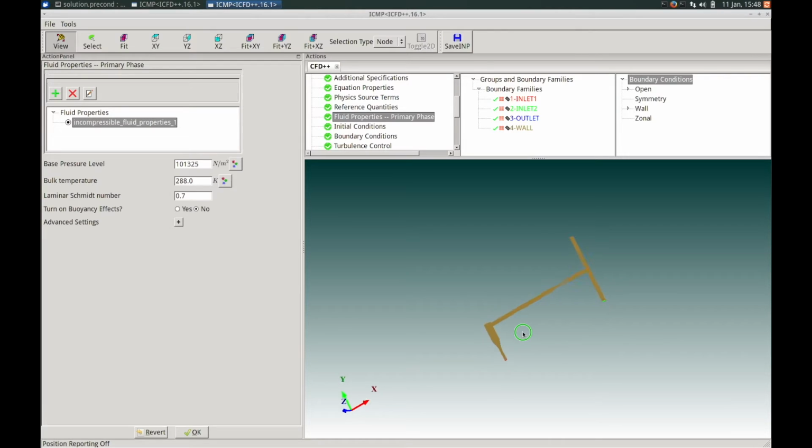Moving the mouse left will result in a counterclockwise rotation, whereas moving the mouse to the right results in a clockwise rotation. You can zoom the view by also holding down the right mouse button, but by moving the mouse up and down. Moving the mouse up zooms in on the geometry, and moving the mouse down zooms out. Finally, the geometry can be translated or panned across the screen by holding down the middle mouse button and moving the mouse in the direction you wish to move the geometry, as you see on the screen.